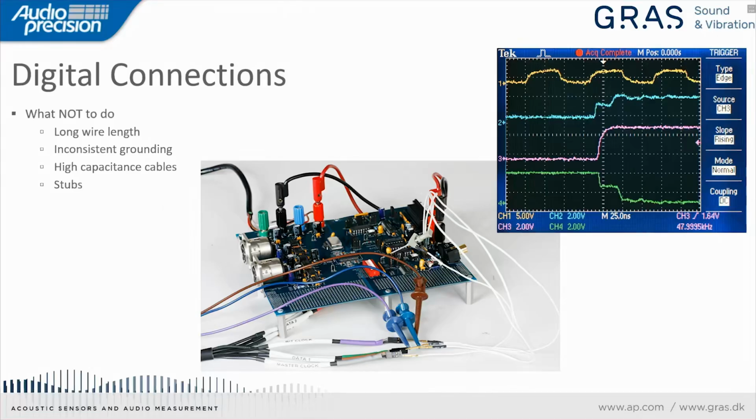So in general, keep your cable as short as possible. Think about your grounding situation. In my particular case, I realize you can't see it physically, but I've carefully set up a star ground where the APX analyzer itself is the star, and I have ground straps for both the digital ground of the EVM and the analog ground of the EVM going back to it.